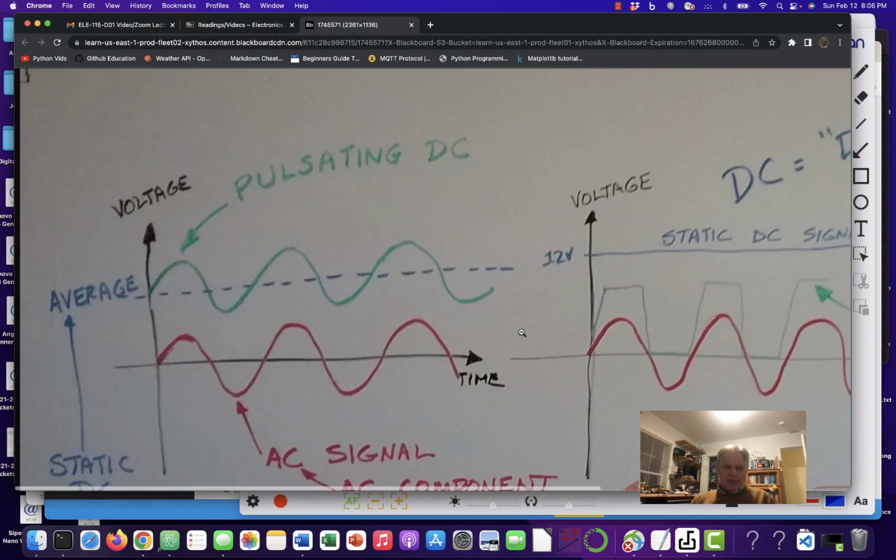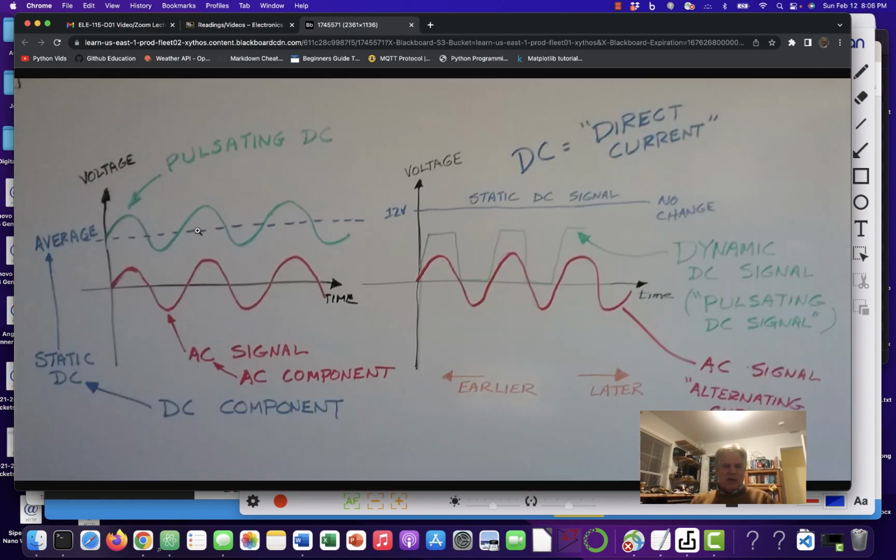So just some vocabulary there, really. I just want you to be aware of that. One thing I said to everyone in lab, maybe didn't make the biggest point out of it, is some companies' signal generators will make it seem like the bottom of the signal is where the DC offset starts. So, I don't think that's our case, but it could be. And so you just want to be careful with a generator. Are these guys truly mathematical, and is the average mid-value of the square wave where we start everything, or do they start everything at the bottom?